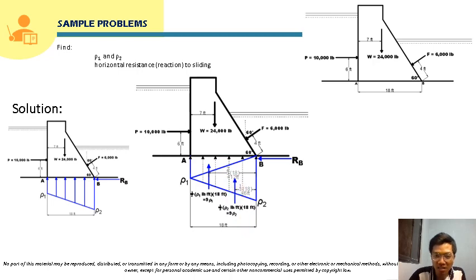Now for this other triangle, its area will be 1/2 base times height. The side that serves as the base is rho 2, and its height is this side, 18 feet. So 1/2 rho 2, with unit pound per foot, times 18 feet: the feet cancel, and what remains is 9 rho 2. This is the equivalent concentrated load of this triangle, in pounds.